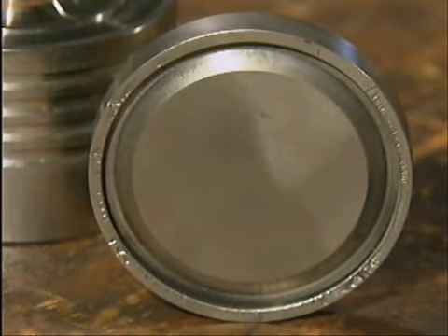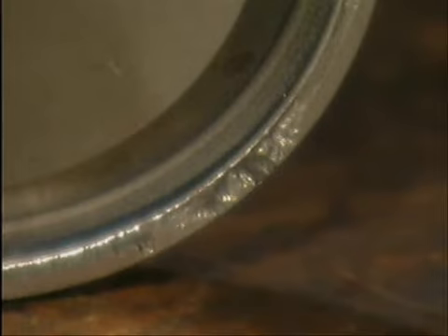up and down. Chattering can seriously damage both the disc and the seat because it promotes steam cutting. Steam cutting occurs when the velocity and the temperature of the escaping steam are so high that the steam cuts into the metal of the valve's disc or seat.